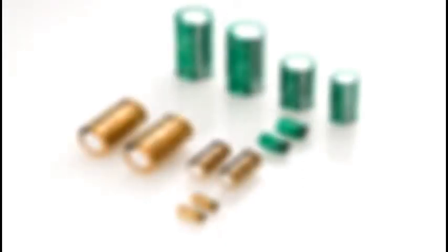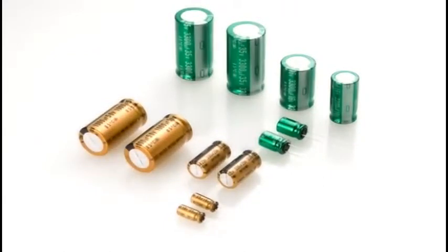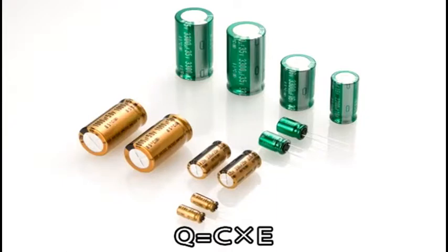When voltage E is applied between the terminals of a capacitor, a proportional electric charge Q is stored in the capacitor. The proportion coefficient C is known as electrostatic capacitance. The following formula is obtained. Q, electric charge, equals C, electrostatic capacitance, times E, voltage.